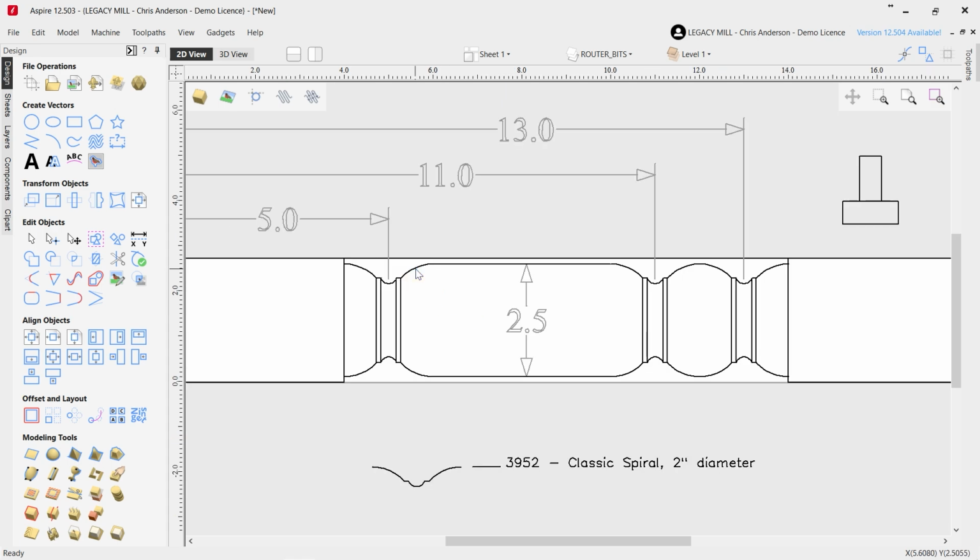One is we're using the same cutter, which we are, same cutter for all 3 of these cuts. We're using the same cut depth, so these are plunging into the material the same depth for each one. And that's tied to the cutter shape, which is why we're using the same cutter. And it's being applied to the same section diameter. For example, if this one here was being applied to 2.5 inches, but these 2 were being applied to a 2-inch diameter section, so they were smaller in diameter, then we'd have to put these 2 on a separate toolpath, and this one would be on its own.